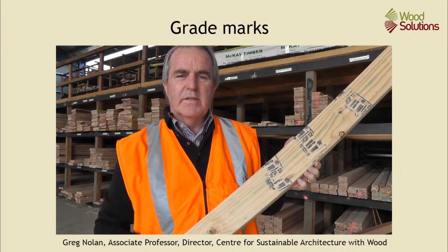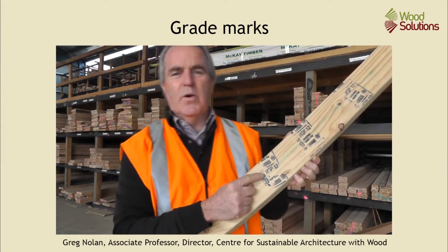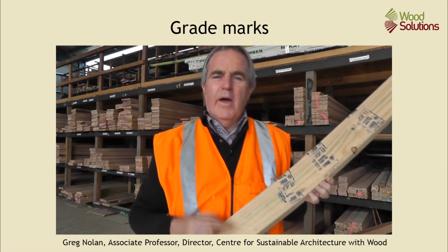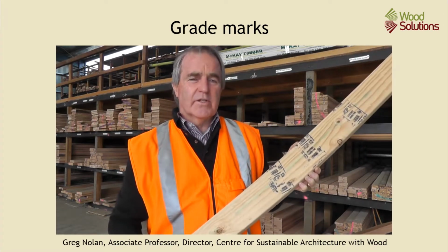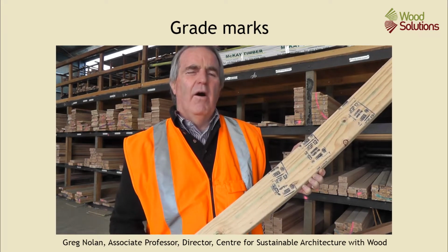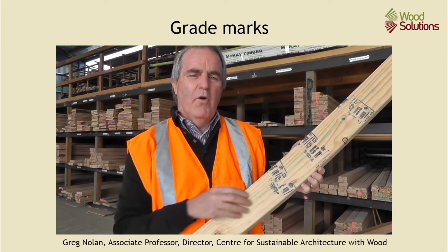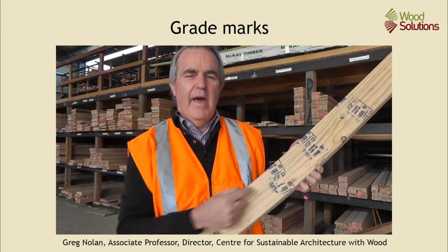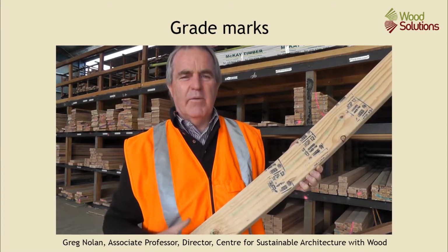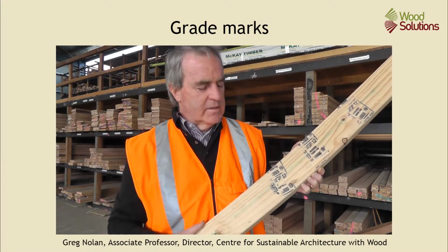This particular piece is graded MGP 12. We can see that here. Now, MGP 12 is a stress grade, and a stress grade gives us a whole lot of values for the performance of the pieces of timber that have that grade. That's in bending, in tension and in compression, and a range of other characteristics.